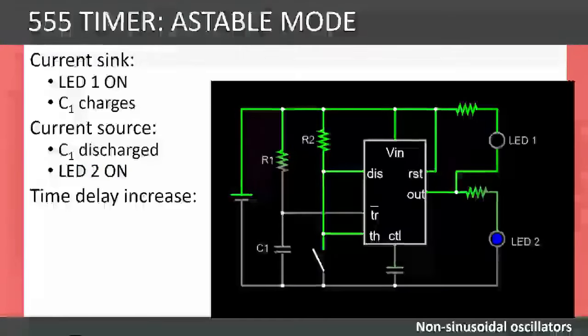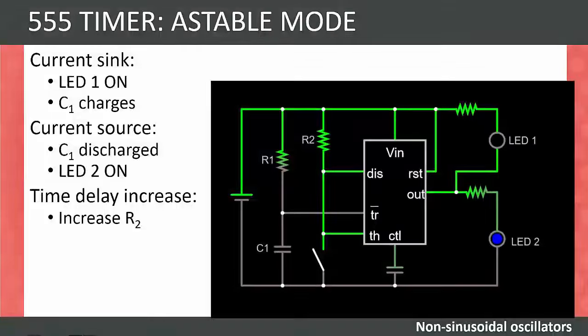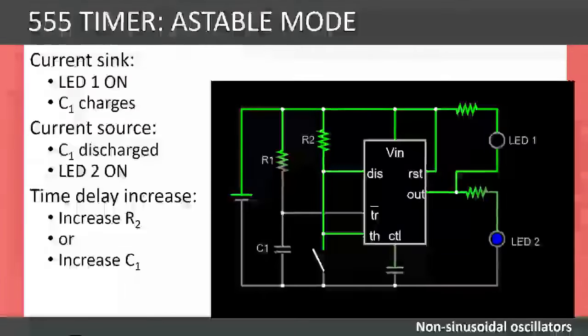The time delay on the circuit can be increased by either increasing the resistor, thus taking longer to fill the capacitor, or it can be increased by increasing the size of the capacitor, thus the capacitor will require more charge to fill it and thus take longer to fill.